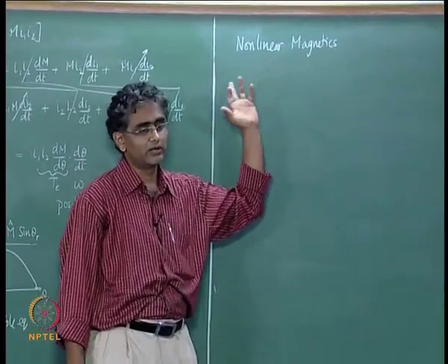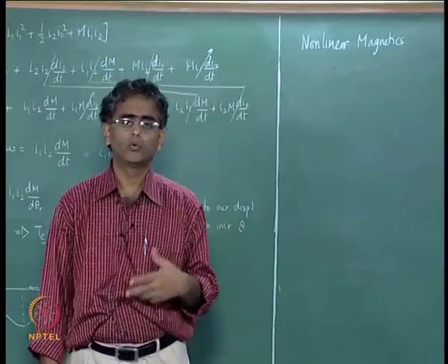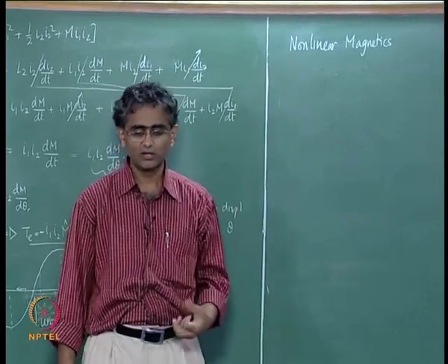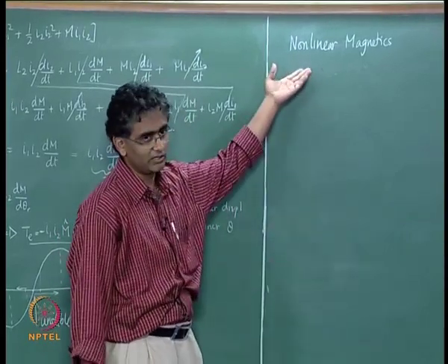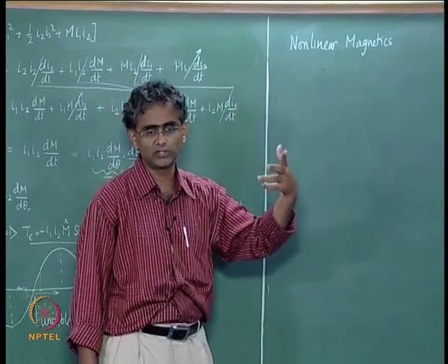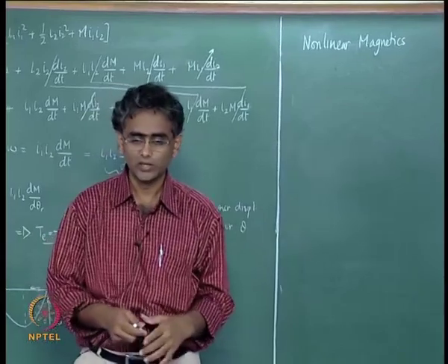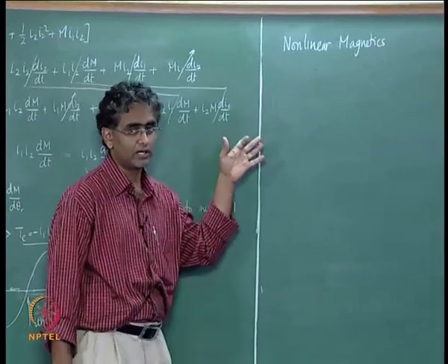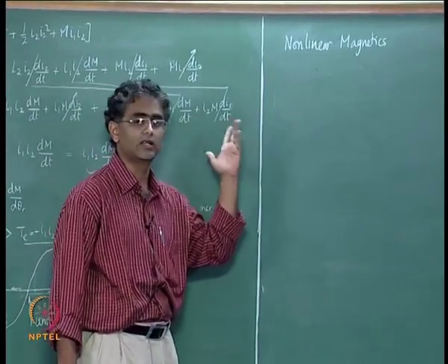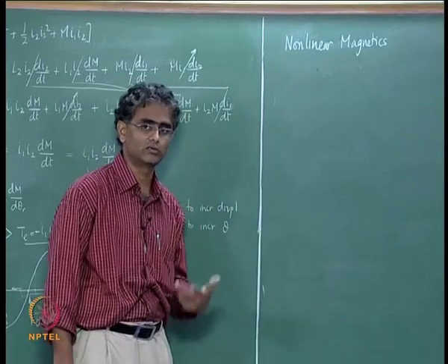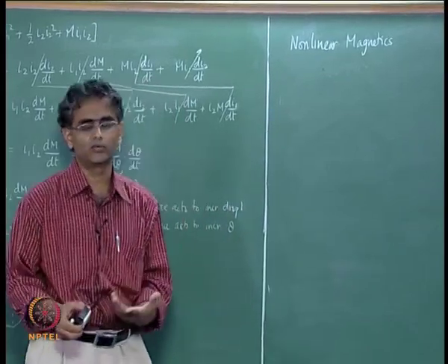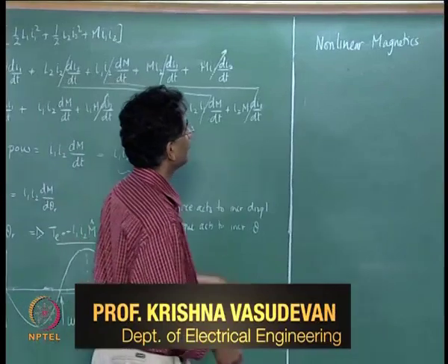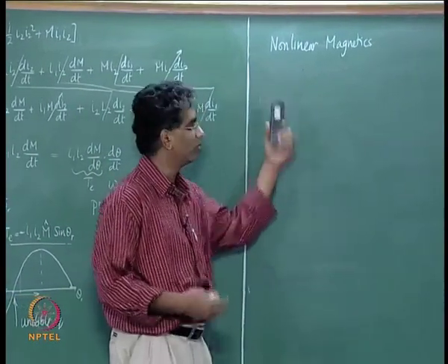it is instructive and it is useful to look for a short while at what will happen if the system is nonlinear, because in actual cases all the systems are of this variety and one needs to know how to handle those systems. It is not easy to handle these systems by analytical means, because the expressions are not amenable to analytical handling, and therefore one has to take recourse to specialized software like the FEM software that we have seen during the various lectures earlier, but one needs to know how to go about doing this.